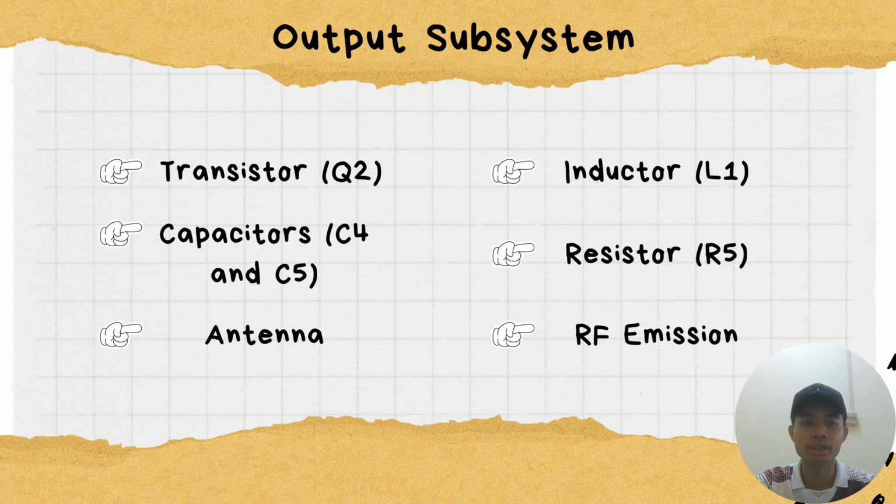Next, the resistor R5. This resistor and the others in the circuit assist in stabilizing the amplifier's performance and determining Q2's operating point. In order to keep Q2's collector from overheating or burning out, it might also be used to limit the current flowing through it.